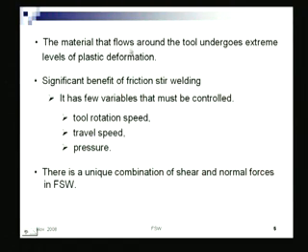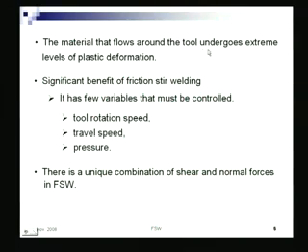You can move the metal as you wish at that temperature, of course. The moment temperature is removed, it solidifies, it becomes hard, solid. So, that is the principle being used here. So, the material flows around, that is why the term flow is being used, though it is not a liquid flow, but it is equivalent to that. So, the dynamics of this material movement can be modeled using the principles of fluid dynamics, right. So, the material that flows around the tool undergoes extreme level of plastic deformation.